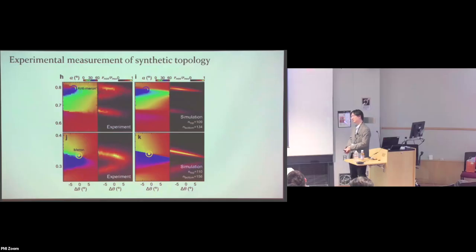Just one other question. When you talked about embedding some Hall bar contacts or something for doing transport measurements, are those entirely on the flat part of the tip? Those are on the substrate. Oh, they're on the substrate. Okay. Are you accessing just the region of material where they're actually in contact, or are you going to end up averaging over some of these regions?